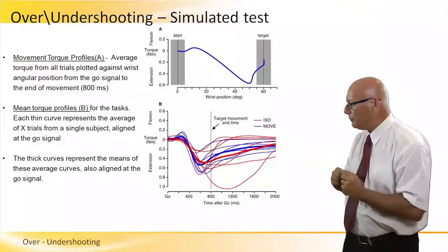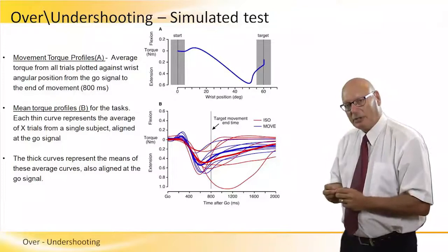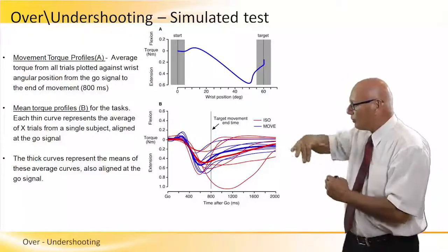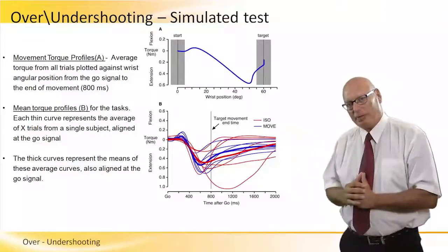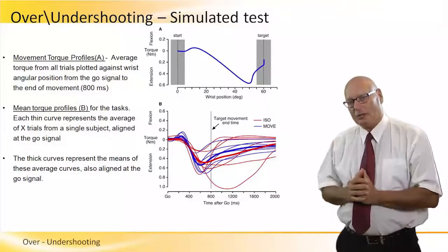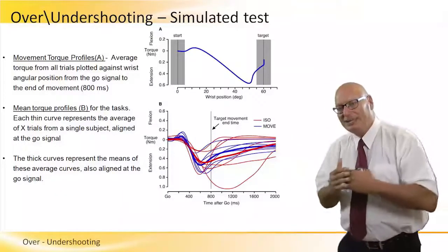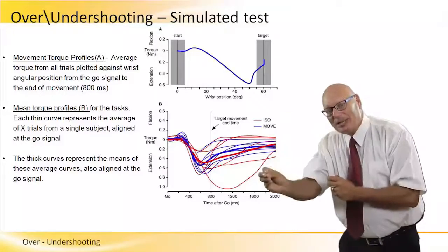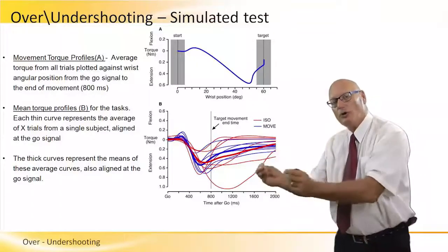And as we can see from a torque point of view, once we have a start, after waiting for about 10 seconds, we get a start command, and the torque goes a little bit high. The torque becomes very negative, below zero, and then when we get to about 50 degrees, we slow down the process, we decrease the torque, and we get to the 60th degree exactly after 800 milliseconds without overshooting.